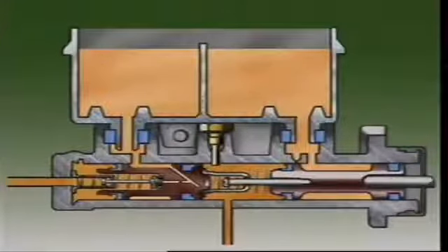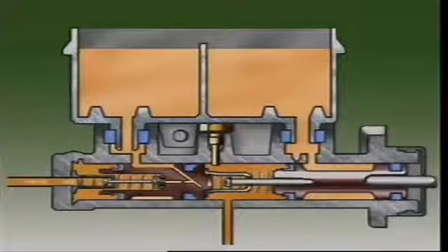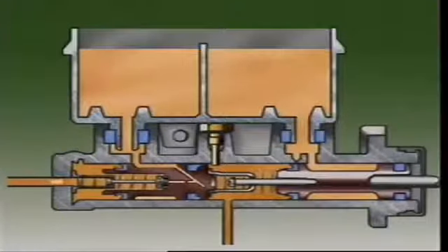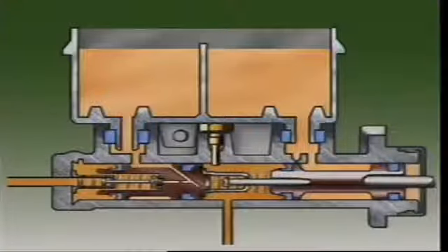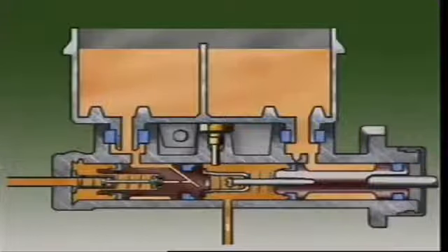If braking conditions are such that the hydraulic modulator must return brake fluid to the master cylinder, then for the front brake circuits, fluid is returned to the front section. This forces the secondary piston back against the force of the primary piston spring and the rear brake pressure. If enough fluid returns, the centre valve opens and allows fluid to return to the reservoir. If fluid is returned from the rear brake circuit, the secondary and primary pistons tend to be forced apart.